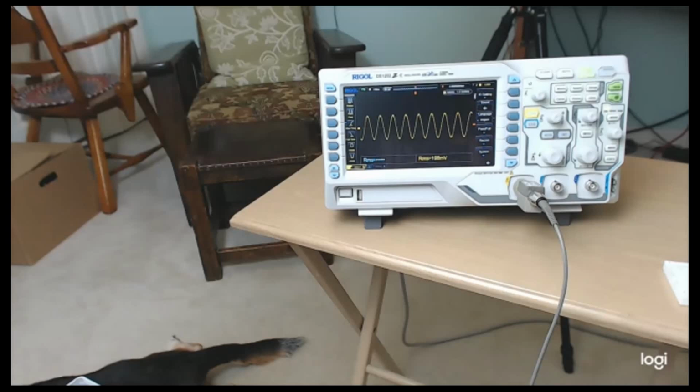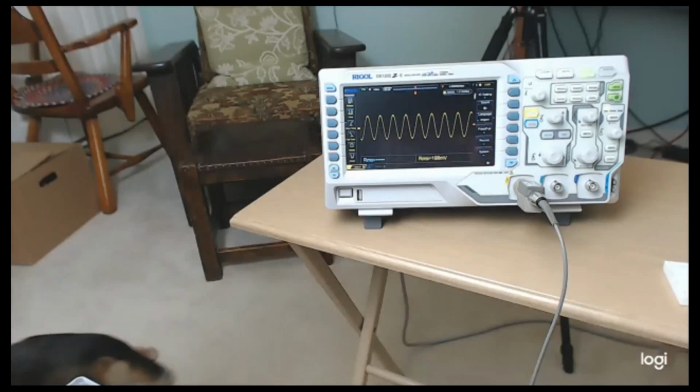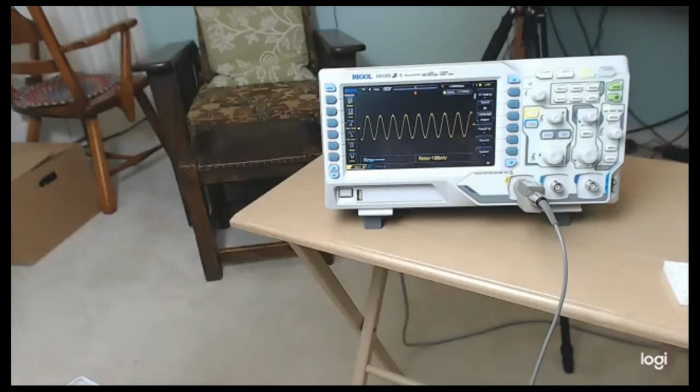But there is no complicated hardware to generate these at all. There's no tuned oscillators and crystals or anything like that. It's all done by making a few adjustments in the software. So very straightforward to do exactly that. And in fact, this AD9850 is used in a bunch of homebrew rigs to do exactly that.